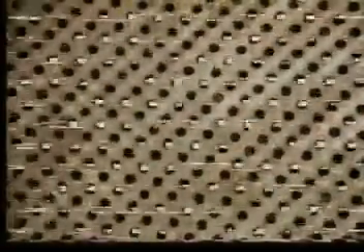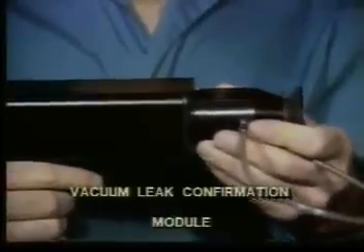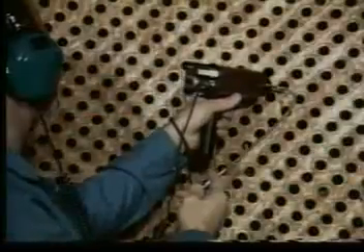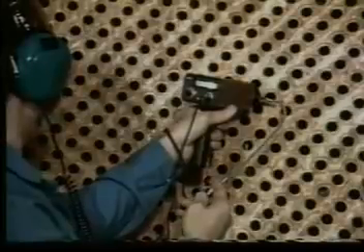As steam rushes across condenser tubes, it generates a noise with ultrasonic components similar to those of a leak. This sometimes confusing sound is called steam impingement. To differentiate between steam impingement and air in leakage, use the vacuum leak confirmation module in place of the regular scanning module. Seal off the end of the suspected tube, isolating it from the rest of the tube sheet. Then listen and observe the meter.